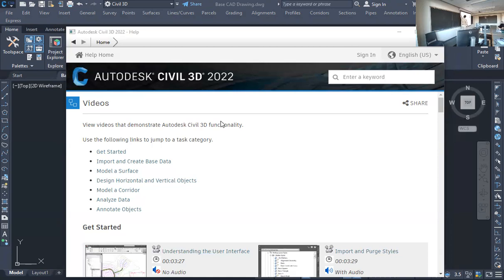So point number, and it has to be a number, northing, easting, elevation, description. The description can be anything. The description can be numbers or letters. But this first column, all the way through the 4th column, those are all numbers. This is just a sample set. This isn't anybody's points. This is my points. Follow what the formatting needs. If it's not this formatting, Civil 3D is not going to import.